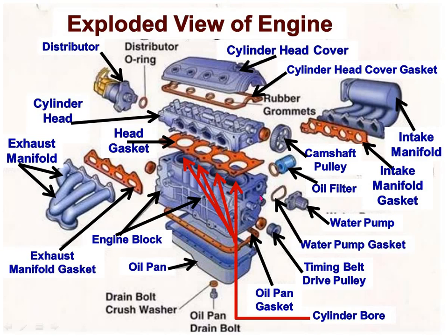According to that, cylinder bores are there in the cylinder block. At the lowest end, there is an oil pan, or we can say oil reservoir, which is attached with the engine block. In the oil pan, there is lubricant oil, which is either lifted or thrown to lubricate the various parts that are reciprocating or working within the engine.